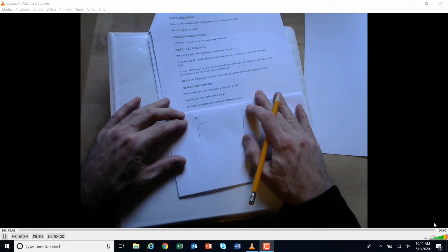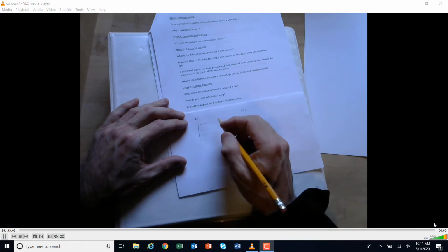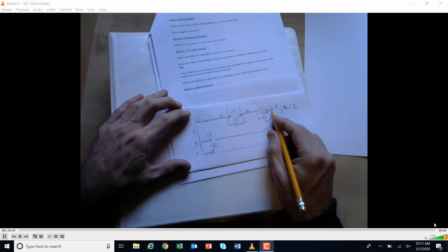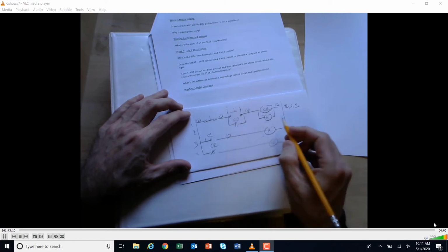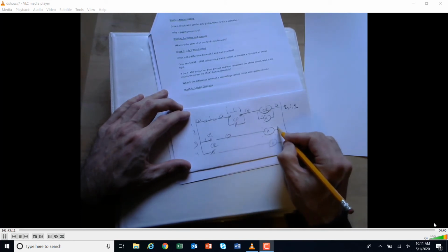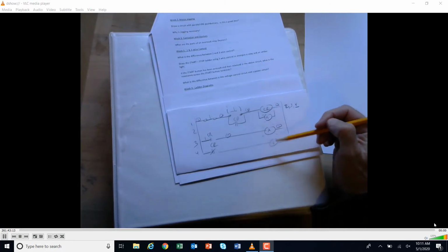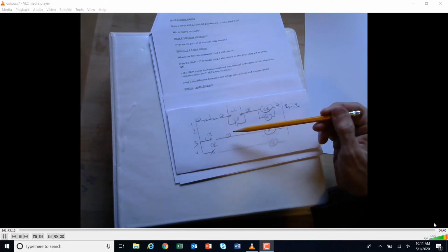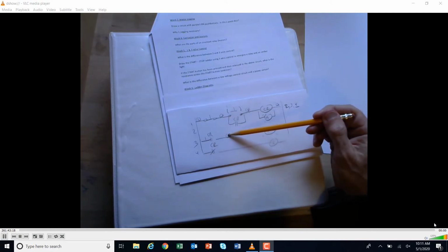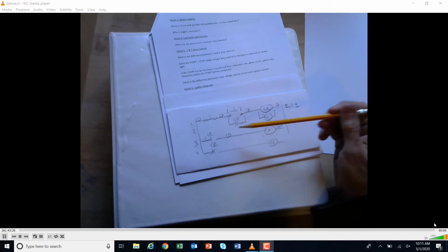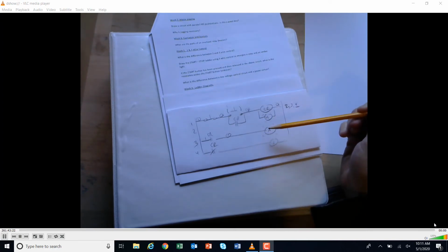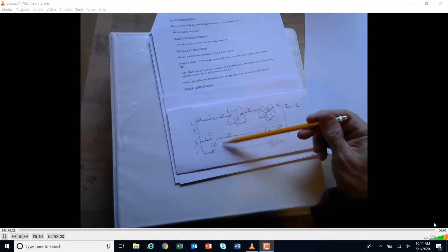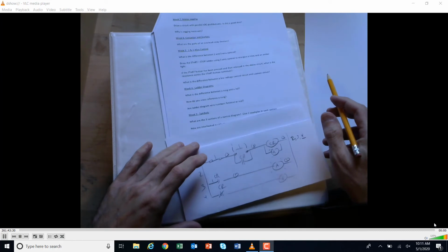Our ladder diagram numbers, fictional or real? Well, just as we talked about right here, when we put these wire numbers on here, we would expect that when we went and looked at this item, this wire here, for example, that was 5 on this end of the wire, and on this end of the wire, we would expect to see a 5 on either end so that we could troubleshoot this, okay? So the actual wiring of the item should match what the ladder diagram is showing.